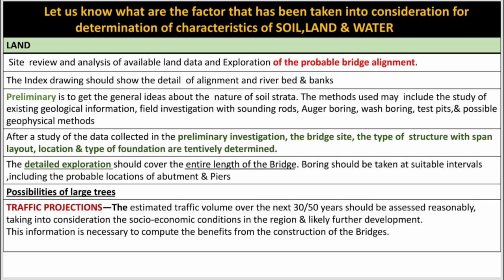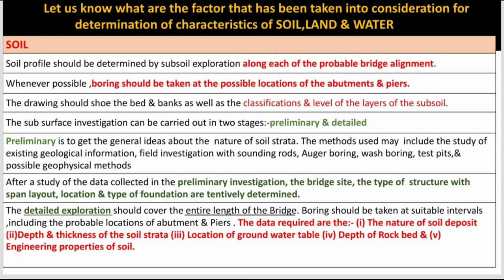So my young generations need to be very careful during the fixing of the alignment of the bridge. Sometimes COS becomes important due to some public demand. So try to identify those changes initially so that they can be taken into consideration if required. In the current new EPC documents, all possible COS should be frozen within 6 months of the contract. But there is always a space, so these things should be kept in mind.